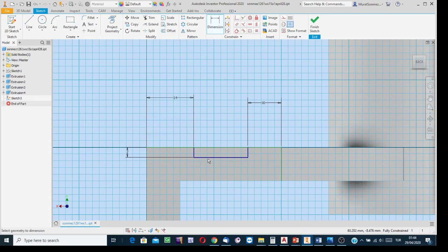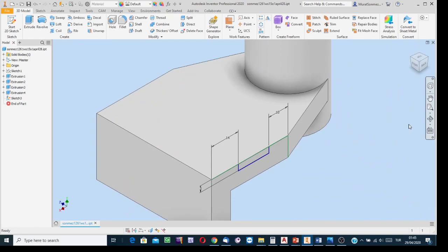And now this line is the edge of a profile surface, this is the edge of the horizontal surface of the channel, this is the edge of the other profile surface, okay? And this green line from here to there, you see, forms a region, a closed boundary, say a closed profile. Size correct, shape correct, and this means the sketching is finished. Finish sketch.